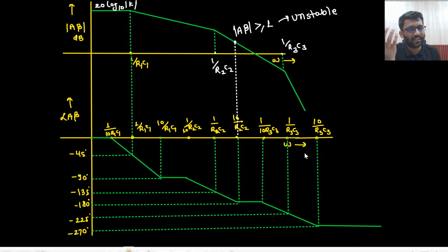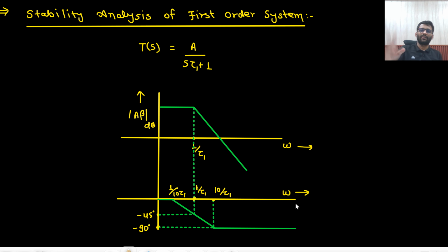In 3 stages, if you are using 3 stages, that means you have very high gain. And if you have very high gain, the roll off will be very less till it reaches minus 180 degree phase shift. And at minus 180 degree, you have very high chance to have gain greater than 1. So that's it. So what did you understand? Stability.